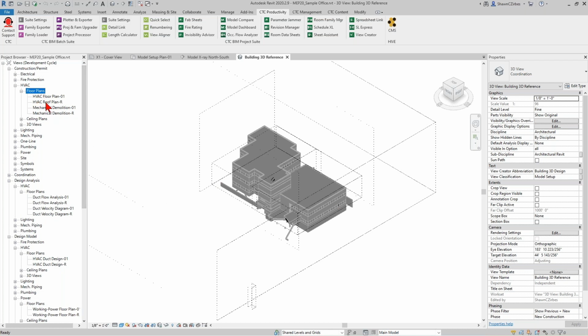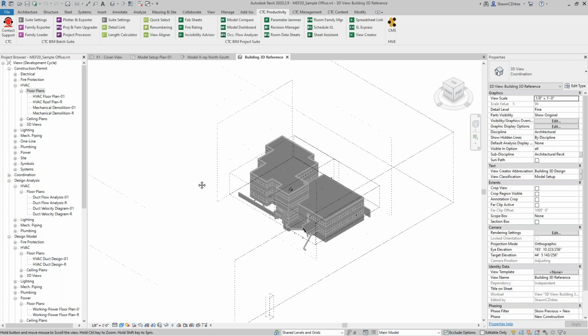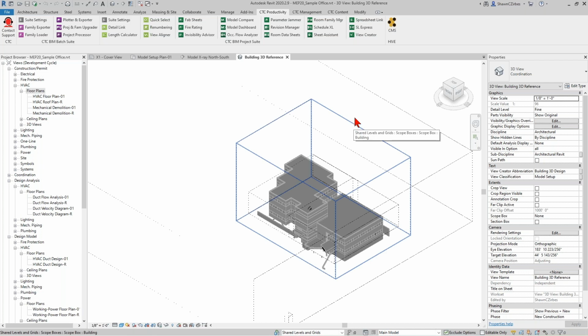I'm going to go through and build out all of the other floors for this particular structure. So basement level, 2, 3, 4, and then if there's anything that I'm missing, or if I get a little lazy and decide to do my level 1s and my roof levels as well, just in case, the View Creator will help me with that process. So let's go through the exercise of building up all of these floor plan views.